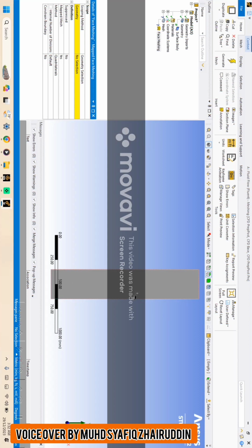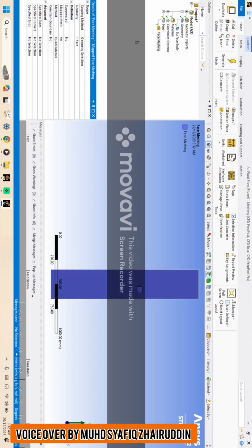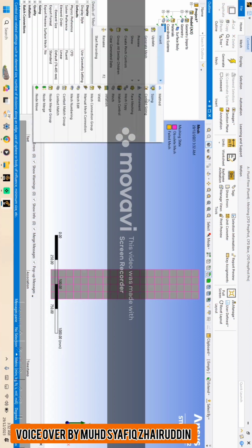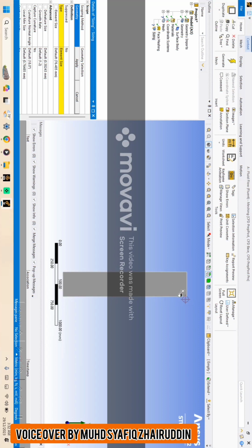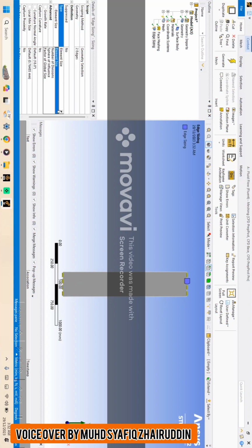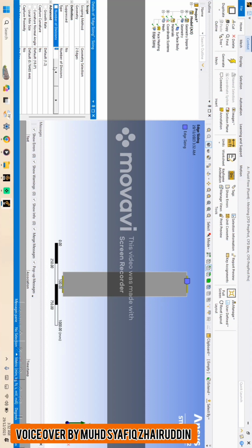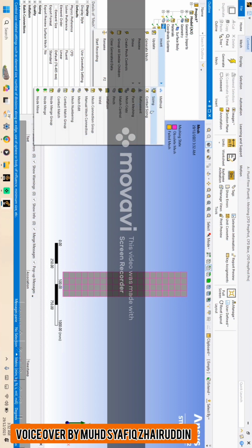Right click mesh, insert the face meshing, select the surface and apply. You click mesh again, insert the sizing on the top boundary, okay, and the bottom boundary. Now click apply. For the type, we choose number of divisions, and for the number of divisions I put 50,